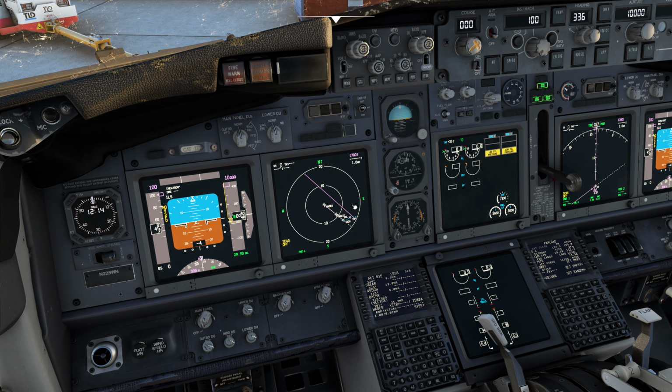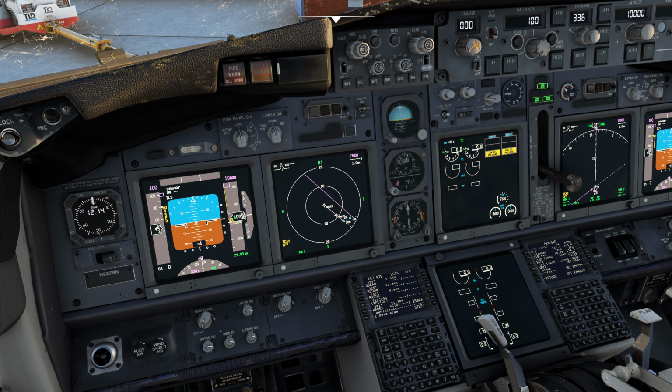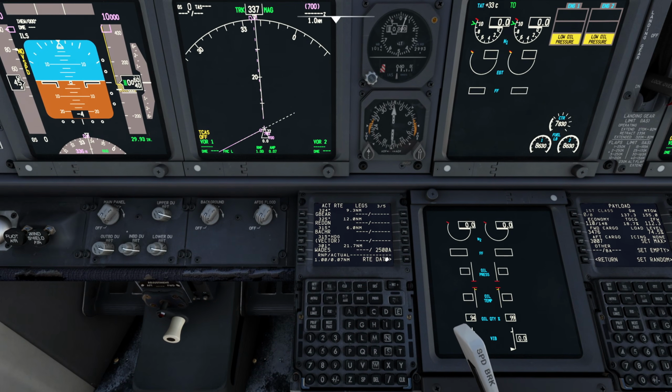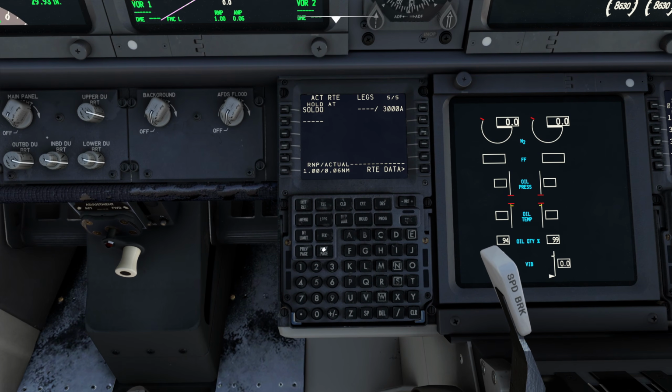flight computer there. And here's where we'd come out like this, and then vectors, turn around vectors into runway 13 left into Dallas. So that looks good. So we can go back to map view, and we'll jump down to the FMC again. And again, you can see all of your waypoints in right there. Okay. So we'll click the legs page again to jump back to the top.